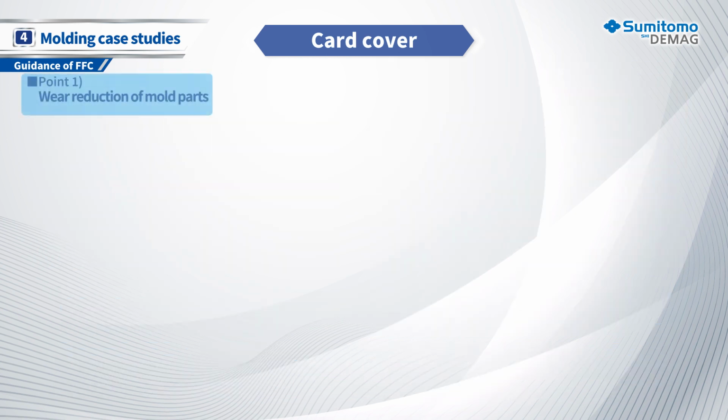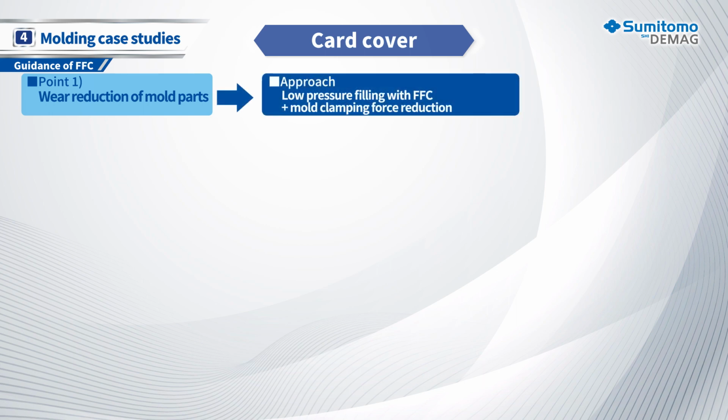First of all, with regard to molds, if excessive mold clamping force is applied during molding, the wear of components will progress. The low-pressure filling by FFC and the resulting low mold clamping force reduces wear on mold components, which leads to extension of the mold maintenance cycle.